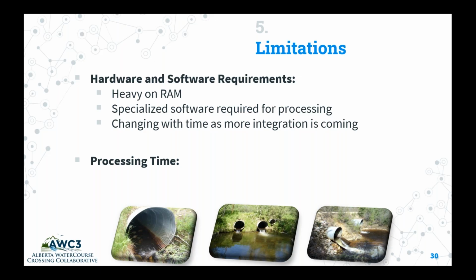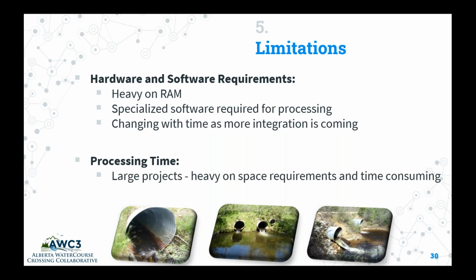Now, the processing time would also vary. Essentially, like any other project, the larger the project, the more resource intensive it is and the more time it will consume. The problem with the terrestrial LiDAR dataset is that the limitation would increase exponentially. Best to capture what is required instead of going for the highest resolution setting.